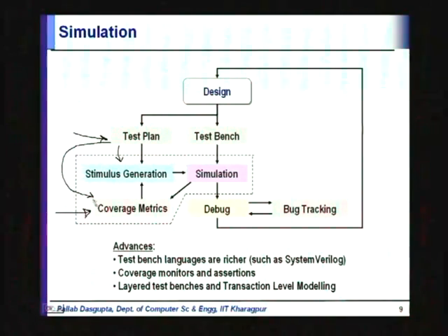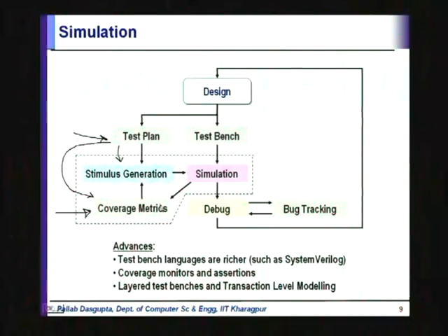Now if you want to check this property, then the first signal must go high at some point of time, otherwise you have not checked anything. So you can express that again as a property here, and they are called cover properties, right. And just like any other coverage metrics, at the end of the simulation you produce a coverage report saying that these properties were checked, these properties were not checked because their conditions never happened. And in terms of simulation coverage metrics like code coverage, transition coverage, etc., a separate report is produced on that. We will study these things in more detail when we go into how the simulator works.